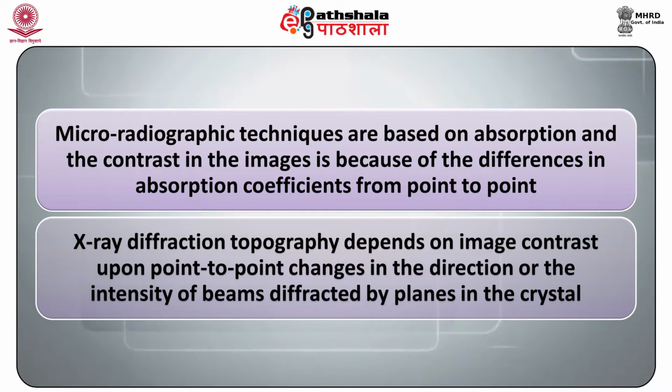Microradiographic techniques are based on absorption, and the contrast in the images is because of the difference in absorption coefficients from point to point. X-ray diffraction topography depends on the image contrast upon point to point changes in the direction or intensity of beams diffracted by planes in the crystal.